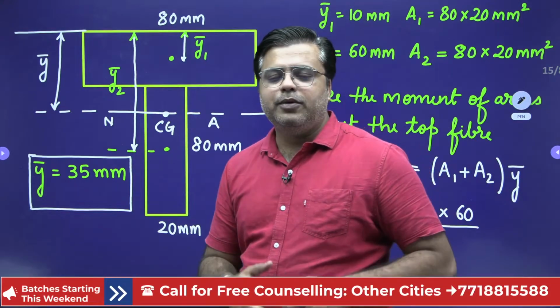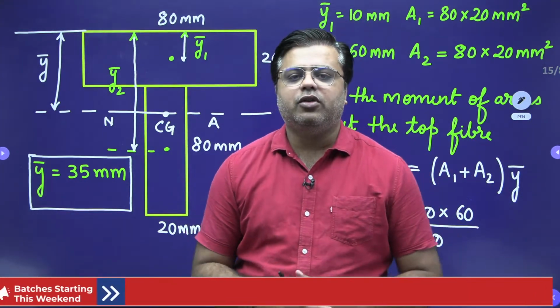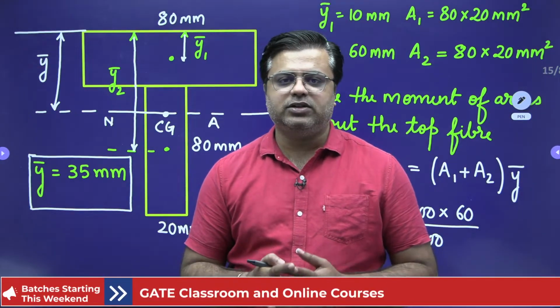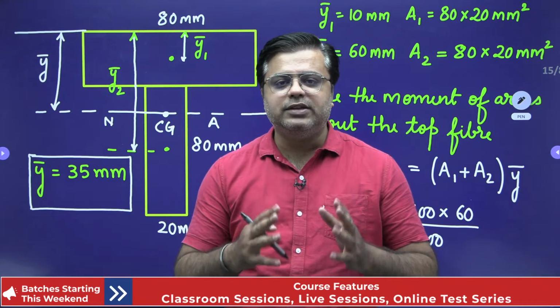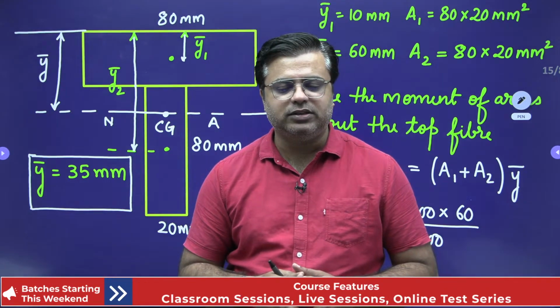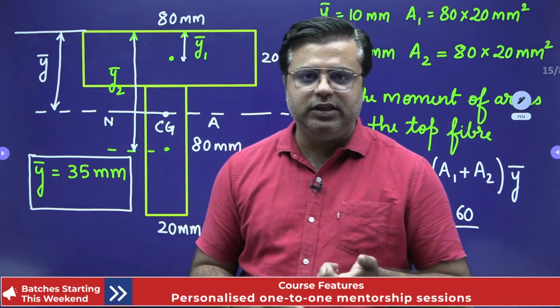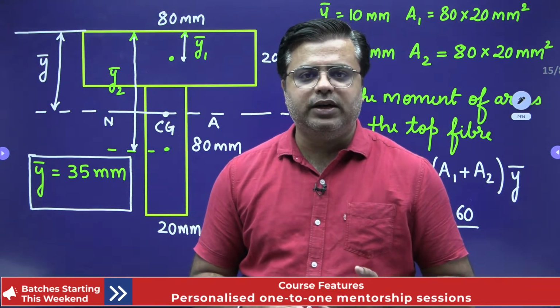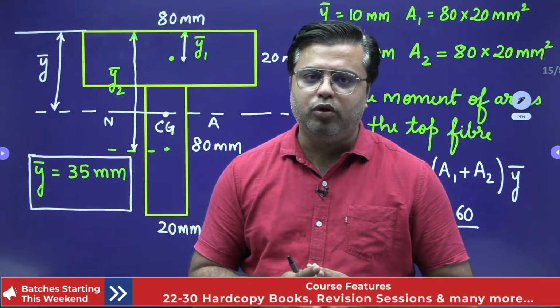I hope you find this session informative in drawing your conclusion towards the bending stresses. Anywhere in the beam, wherever your shear stress is 0 and bending moment is constant, in that span only you will have pure bending.